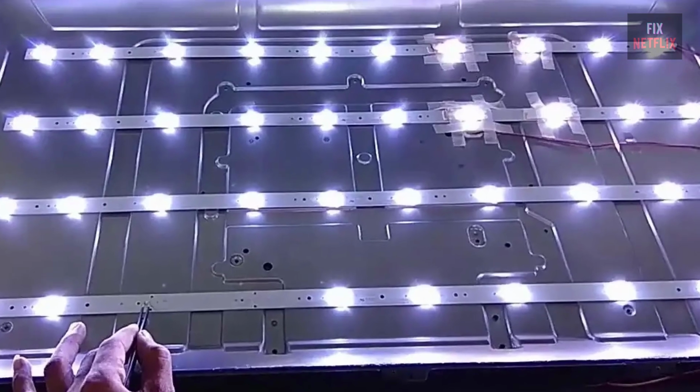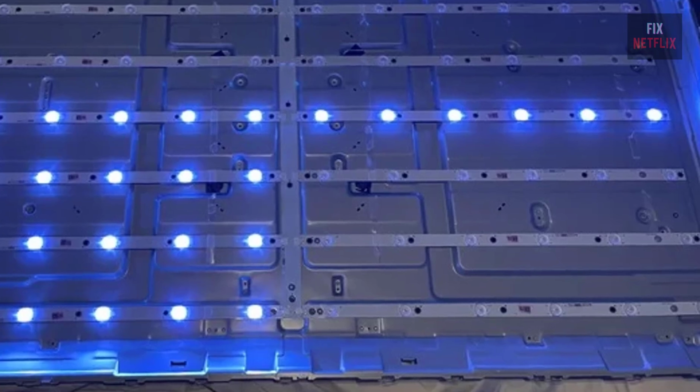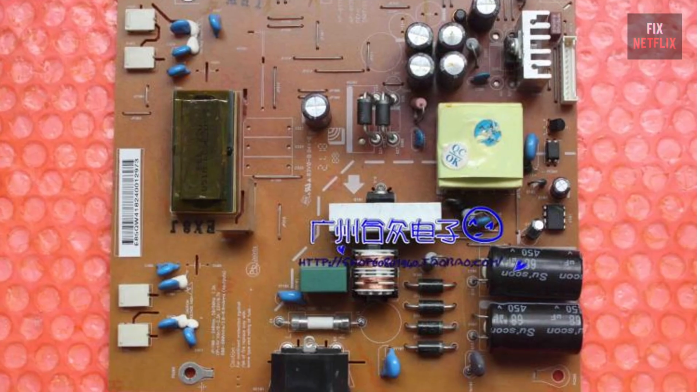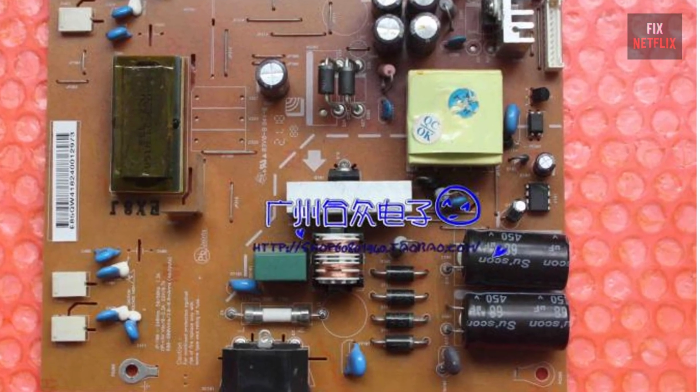The TV will likely not give blink codes or any other trouble sign. You can replace backlights with aftermarket parts that are available. If you don't see an image, you need to determine if your power supply is bad.